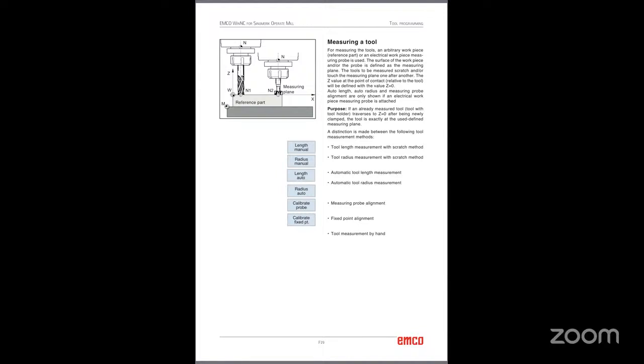Next, measuring a tool. So tool measurement means measuring the actual length and radius and entering into the control system is what is called a measuring tool. This is very important. Make sure to ensure that the measurement accuracy is correct. Why tool measurement? If the machine knows the length and the radius, then the machine will be accurately carried out.